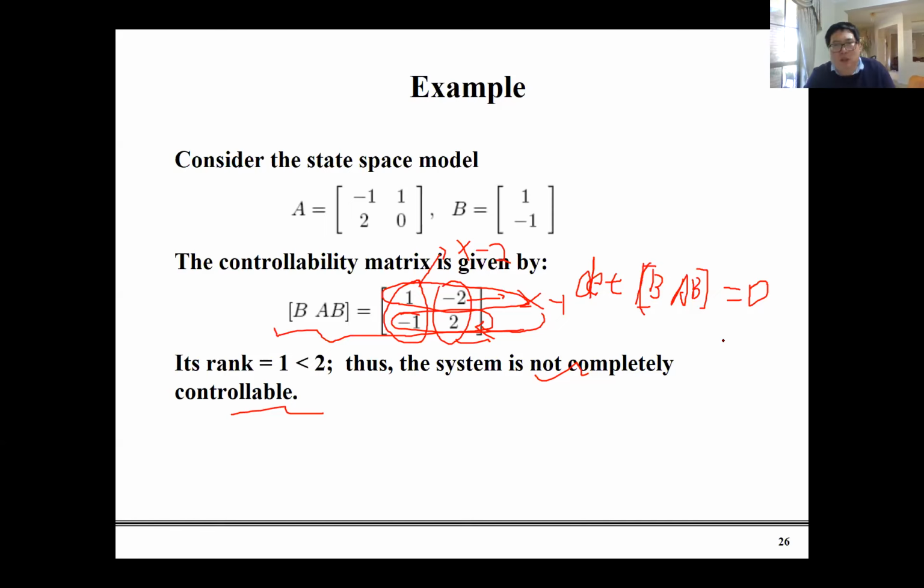So suppose you have a system, then maybe the first thing is you can check if the system is controllable or not, right? If the system is stable or not. Then if it is not stable, you want to use a state feedback control and pole placement to make it stable, right? But before you do that, you need to check if the system is controllable or not.